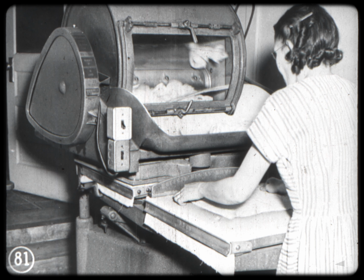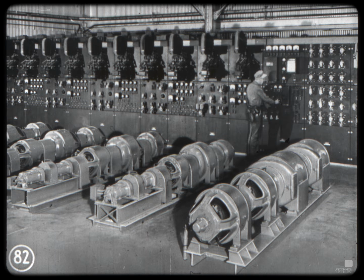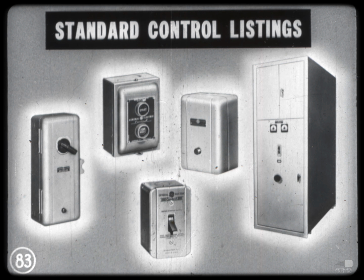For a machine like this handkerchief ironer, where the load is non-reversing, probably a simple switch to throw the motor across the line is all that's needed. On the other hand, a cold strip steel mill requires this elaborate combination of magnetic control devices, electronic equipment, amplidynes, and motor generator sets, so the equipment can operate over a wide speed range with precision control at any point. By and large, however, fairly simple control will handle most drives, and this is available from standard general-purpose listings.